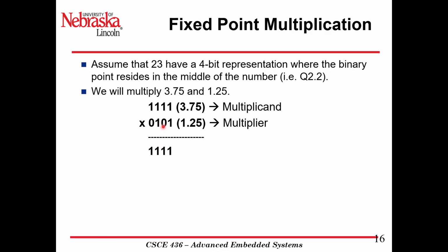Then we're going to shift left by 1, so we can start looking at the 0 bit, that second bit digit. And then multiply 0 by anything, it becomes 0, so we just put 4 zeros in here. But we shifted left by 1, right? Shift and add. Next one, we have 1, shift left once more, 1 times 1, 1, 1, 1 on the top gives us 4 1s.